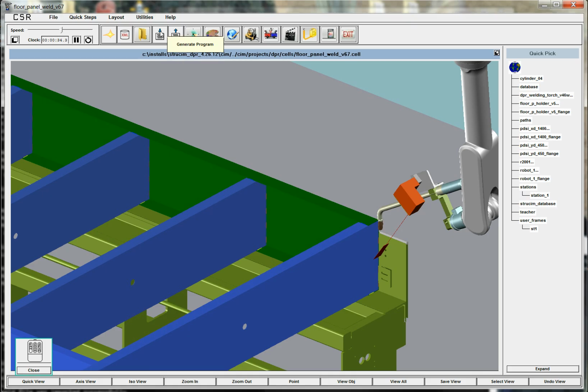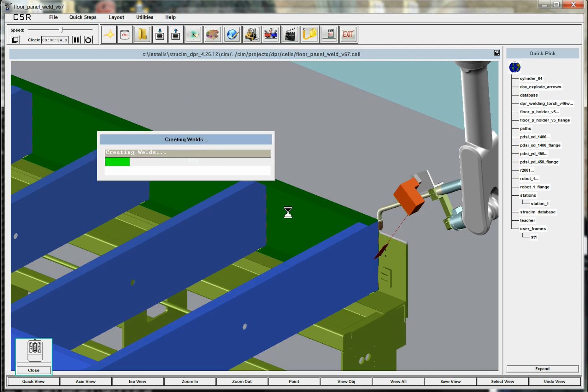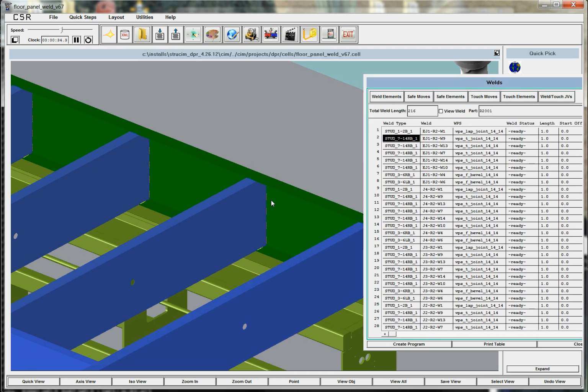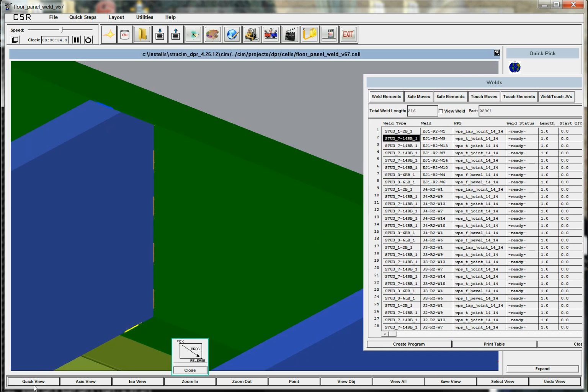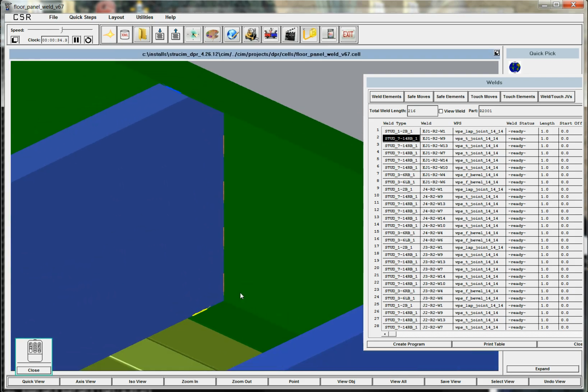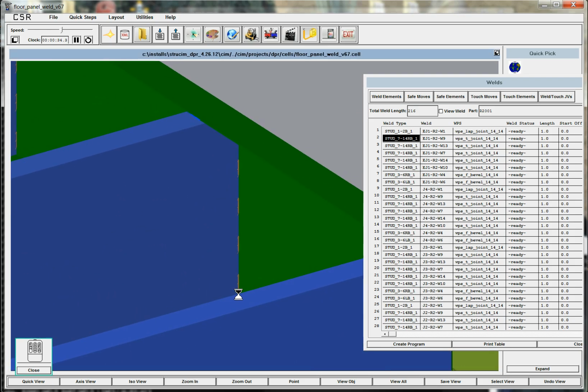So what we do is we get the welds generically, just as their position, and then we go through and find out which two shapes, which two beams, which two framing structures are going to be welded. We look at the normals of those and bisect them so that we get a reference frame on how we're going to weld this. We might not weld it at 45, but at least we have that represented here.